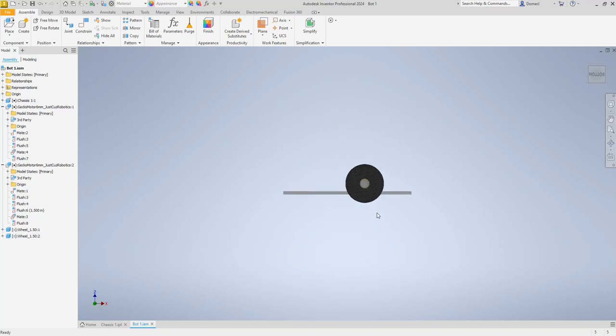So right now, if that's where the motor was, does my wheel have ground clearance to the ground? Yes, it does. Do I want that much ground clearance? Probably not, because again, if you can get another bot under you, well, they have a chance of lifting you or throwing you. So we probably want a little bit of ground clearance, like an 1/8 inch maybe. Not much more than that typically.